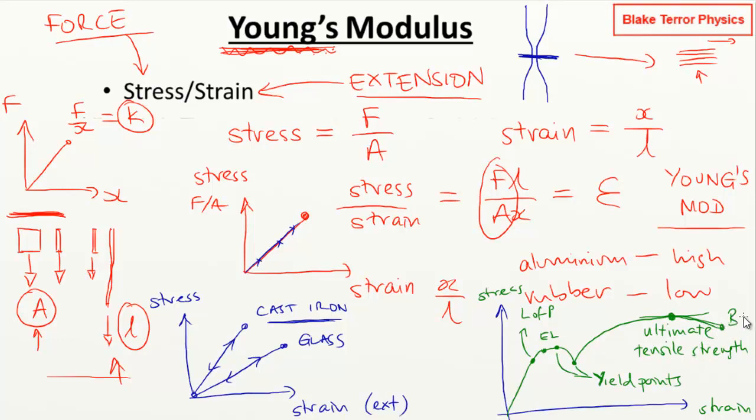This is the breaking point when we get up there, which is the maximum strain that the material can take before it breaks. But if you're an engineer, you're not wanting to get into this crazy area. You're not wanting to be thinking, oh yeah, here's the ultimate tensile strength of this material, so let's load it up to the max, because it's going to start falling apart. This is not a sustainable construction that you've got then.